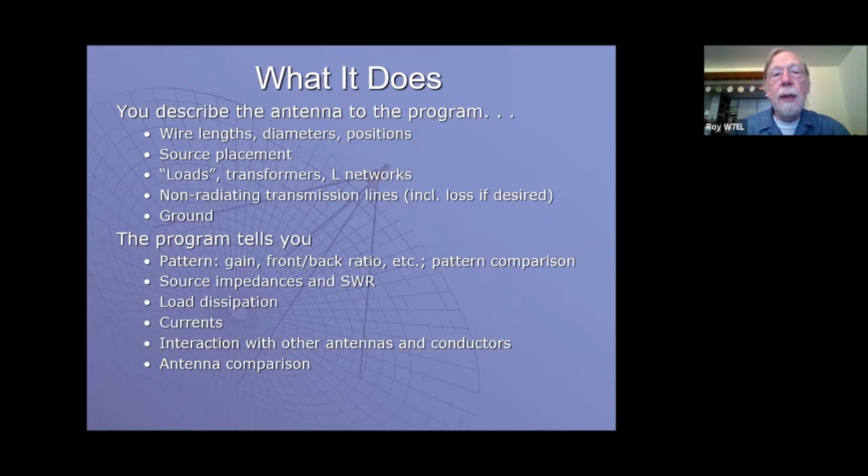And you can easily compare antennas with EZNEC. Richie mentioned the FCC RF exposure requirements, and I believe that FCC accepts EZNEC results for evaluating the fields that are produced by an antenna. When you do try to do the near field analysis with EZNEC, you'll see a disclaimer saying that EZNEC can't be used for determining human safety. And that means that whatever you see with EZNEC, it's not telling you whether it's safe or not.